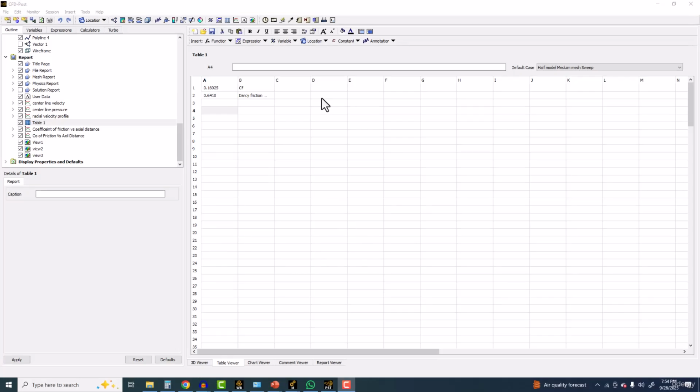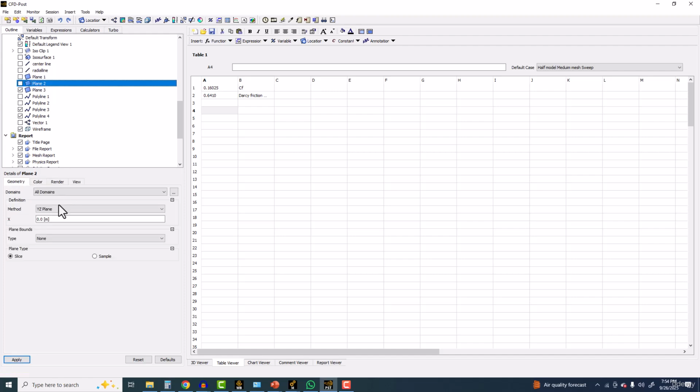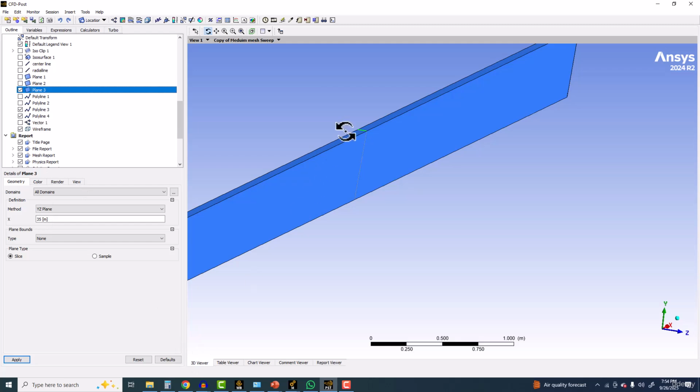Actually, I found the solution. The problem was that when we were making the polyline, this is from plane number 2, but plane number 2 is at Z35. When we have the axisymmetric case, the axis along Z is along the X axis, but in our other cases the axis was along the Z axis.